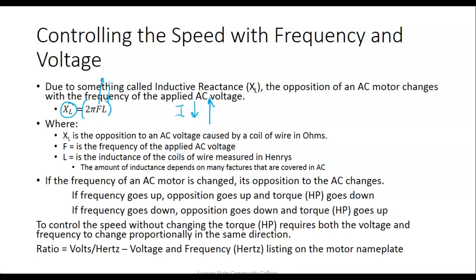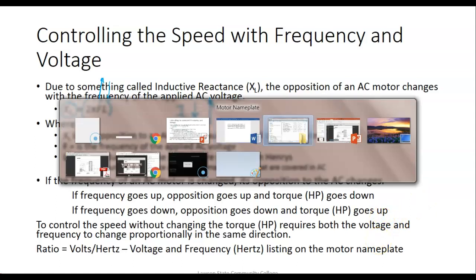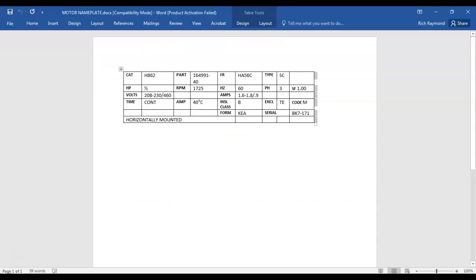So what we have to do when we program these variable speed drives is we take that chart I said, and this is all you do, it's real easy, you enter two things. Well, that's not true, but the two things you enter are the voltage and then the frequency. And then it calculates what they call a volts per hertz.